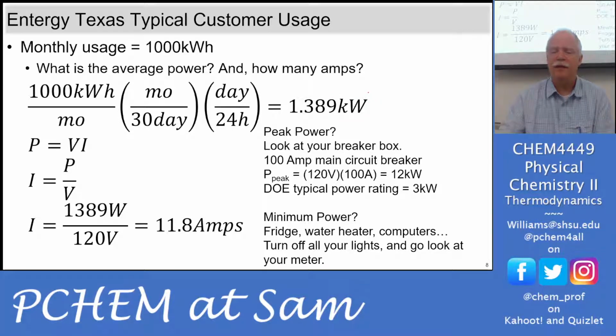And you can find these generators for your whole house. Typically, they get up to around 7,000 watts for a whole-house generator, so that you can handle what they call the inrush current. Whenever the air kicks on or whenever the freezer kicks on, to turn those compressors there's a quick burst of current to get those compressors started, and that will trip the breaker on a smaller generator, so you need a little bit bigger one.